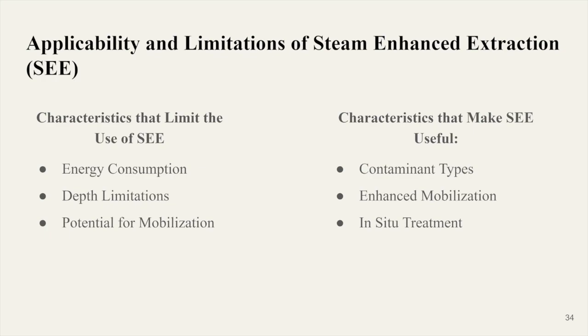The effectiveness of SEE may be limited by the depth of concentration, as steam penetration may be insufficient to treat contaminants located at significant depths within the subsurface, and the potential of mobilization. There are risks of mobilizing contaminants during the steam injection process, particularly if they are volatile or mobile, which may mean we need an additional containment or treatment measure to prevent off-site migration.